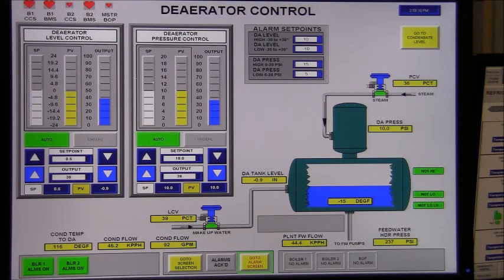PV and set point are both scaled the same. Set point of 10 puts us in the middle of the set point bar graph, displayed down here. The PV now is right on the set point. It's also at 10 inches. PV bar graph is right in the middle. And to maintain that pressure, the steam control valve output is 36%, which is shown up here.